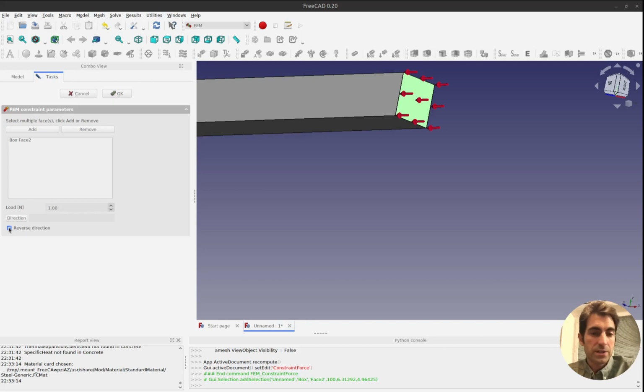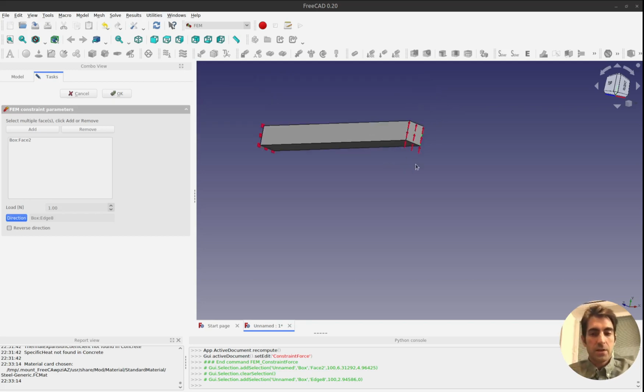It's kind of like pressing into that. I can also try to select the face or edge and then make a direction. See, it is now directed along this face, so it's more like a bending beam. If you hold here and then apply a shearing force in this direction, then this beam will bend. So let's use that one.